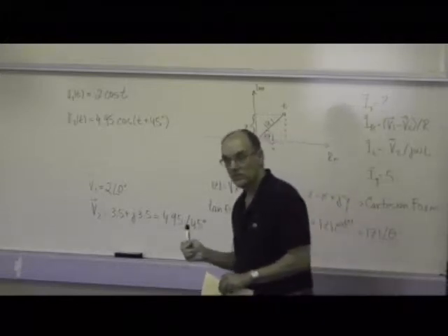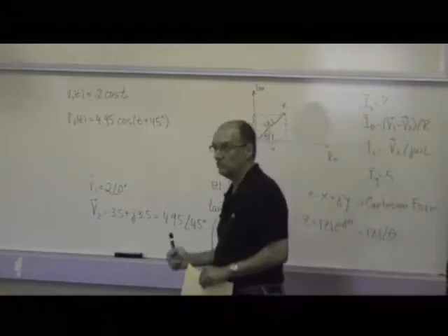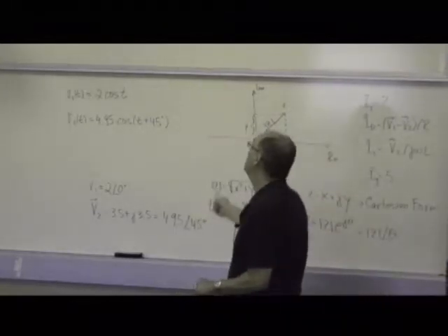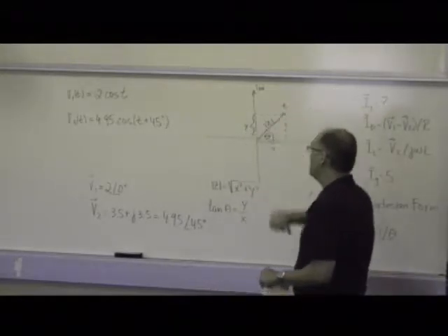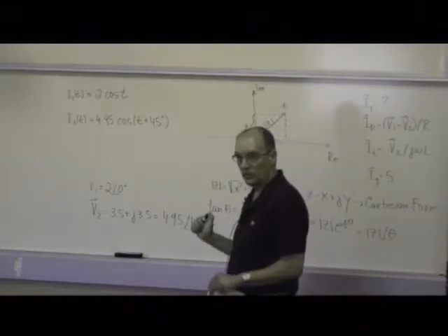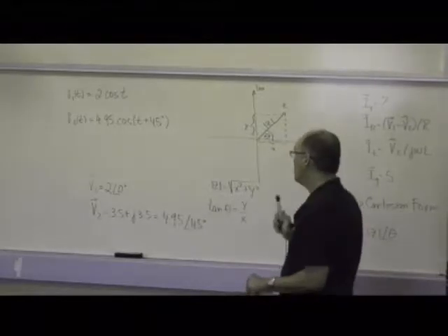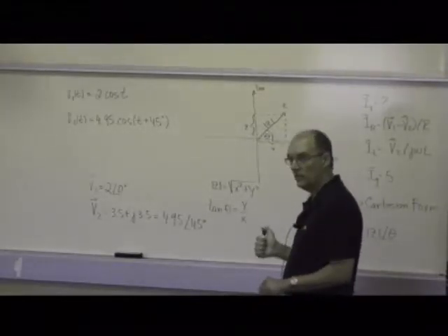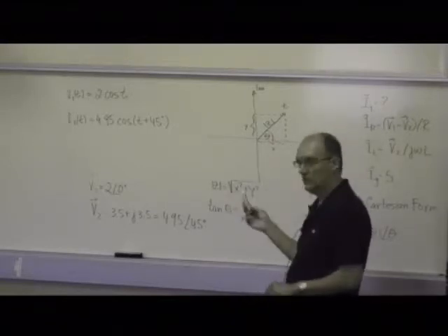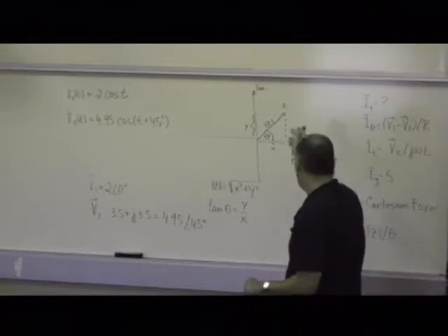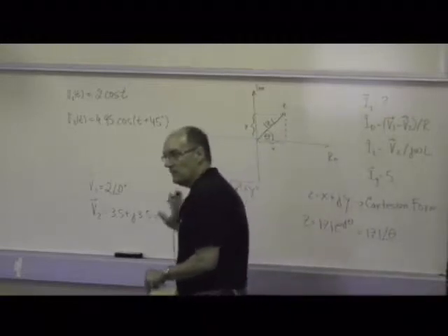The advantage of phasors, of course, is that you don't have to solve differential equations. Everything that I've done so far is algebra, and it will remain algebra as long as I'm interested in steady-state response. So this is basically what the node voltage method boils down to. What I suggest we do is I'll go over a couple of additional problems and make it a little more difficult and interesting. I'll put in things like controlled sources. We will look at Thevenin equivalents and things that are associated with that. Make the whole thing messier, but since we're dealing with matrices, that really doesn't matter too much. Do you have any questions about this?